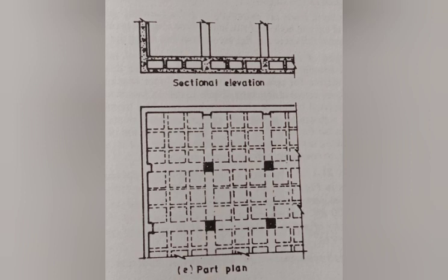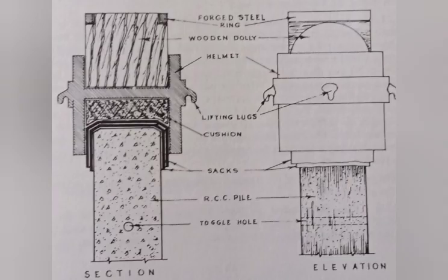This is a picture of two-way grid cellular float type raft foundation. Raft foundations are considered suitable for sites where large amounts of hydrostatic uplift have to be resisted and the building has a basement. Pile foundation is under deep foundation and the types are timber, steel or concrete.